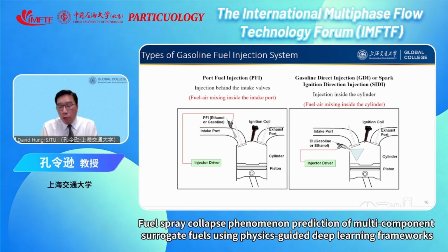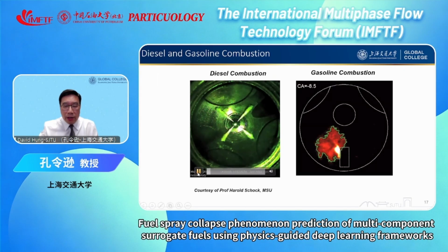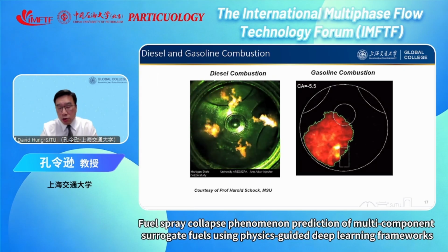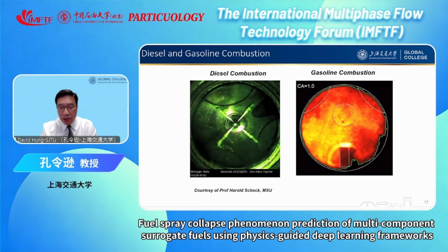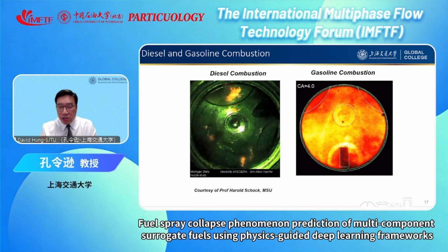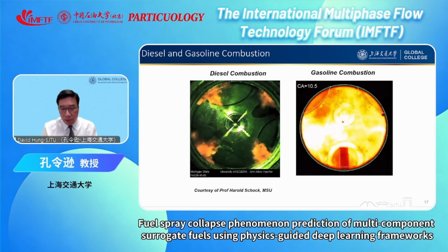We always have an interesting situation where we want to study how good the mixing is. So I showed you two images. The left video is a combustion of a diesel engine, which is very common. You can see the injection happens in the cylinder, right? And then the flame starts from the tip of the cylinder wall where the mixture homogeneity is right for combustion.